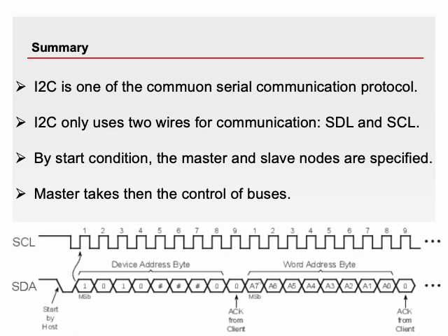In this video, I explained I2C as one of the common serial communication protocols that uses only 2 wires for communication, namely SDA and SCL lines. We explored briefly the topology of an I2C communication protocol and its different components as shown in this figure. I will continue in the next video on how to use I2C communication to collect accelerometer and gyroscope data from a 6 degree of freedom IMU, inertial measurement unit, sensor. It is noted that SDA and SCL idle state is high. I have not explained here the pull-up resistors and different bus speeds, and this may be done in another video.